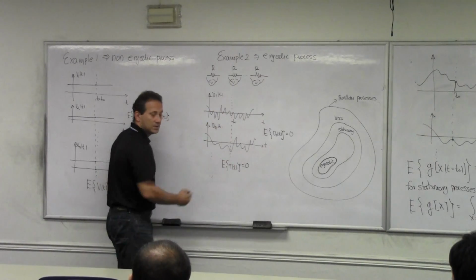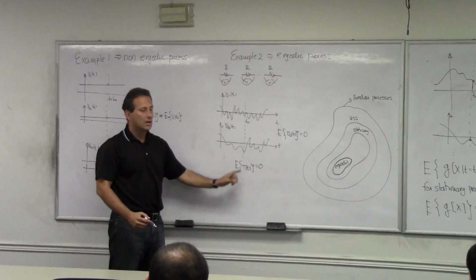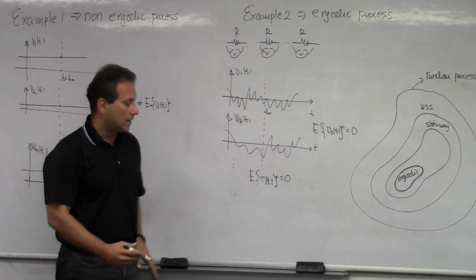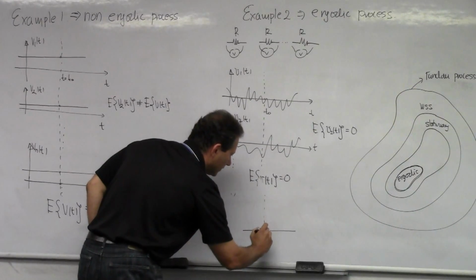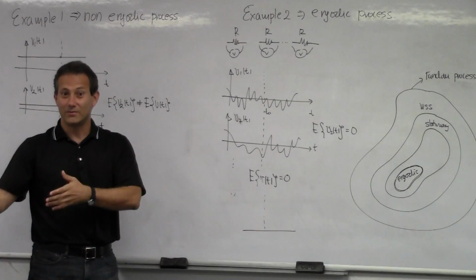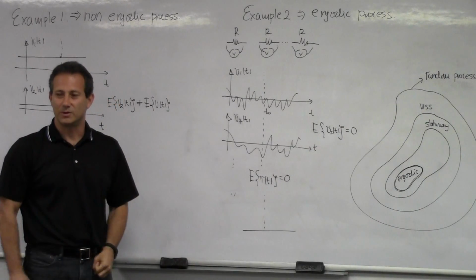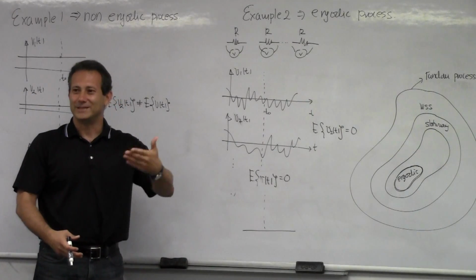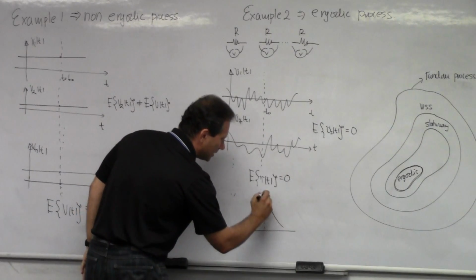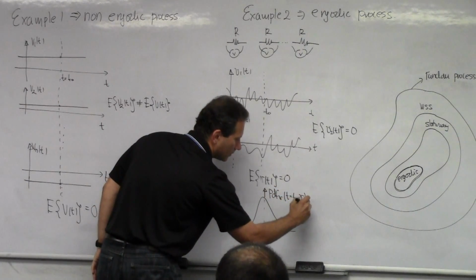Let's take a look at time t0. There are infinitely many of these resistors, right? So now I cut the time, and I record the samples at any given time. That sample becomes a random variable. And whenever I say random variable, the immediate thing is PDF, right? The random variable travels with its PDF. The PDF is what describes the random variable. It's kind of like a driver's license attached to a random variable. So here's the PDF that I obtained for this random variable, the PDF of this voltage at time t equal to t0.